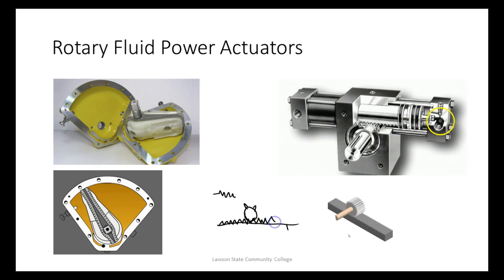It's got a double acting cylinder up here, and when it pushes one way, it takes the rack and moves it some way and causes the what? Causes the rotary gear or the pinion to turn. Or we could do it the other way. Like the old steering wheels on cars. This is the way cars used to steer. So you turned your wheel, you moved the pinion, and then it had the rack that actually did what? Turned your wheel.